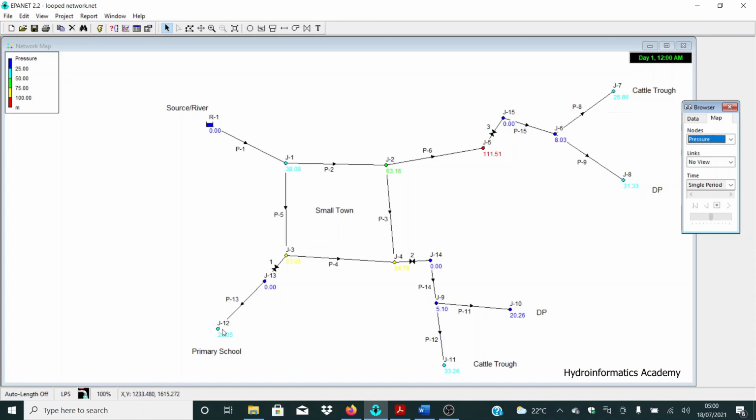That is very important. So in this EPANET tutorial, I'm going to show you how to optimize your model just to make sure that you are having velocities, pressure, and unit head losses within acceptable values. Not just that, I'm going to show you how to use break pressure tanks as a way of dealing with these huge pressures.